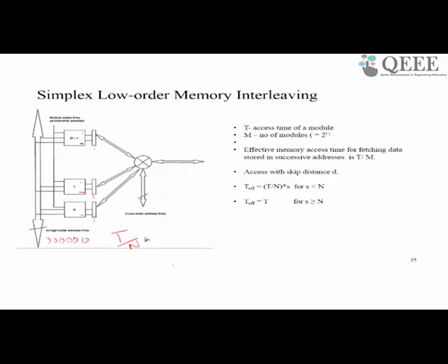Now we change the address to the next location, 0001, in the higher order. Then all these modules will start fetching data from their address location 1 in parallel and provide it after a duration of t. Before that, the first set of data which was fetched and stored in the latch has to be taken out using a router or mux circuitry.